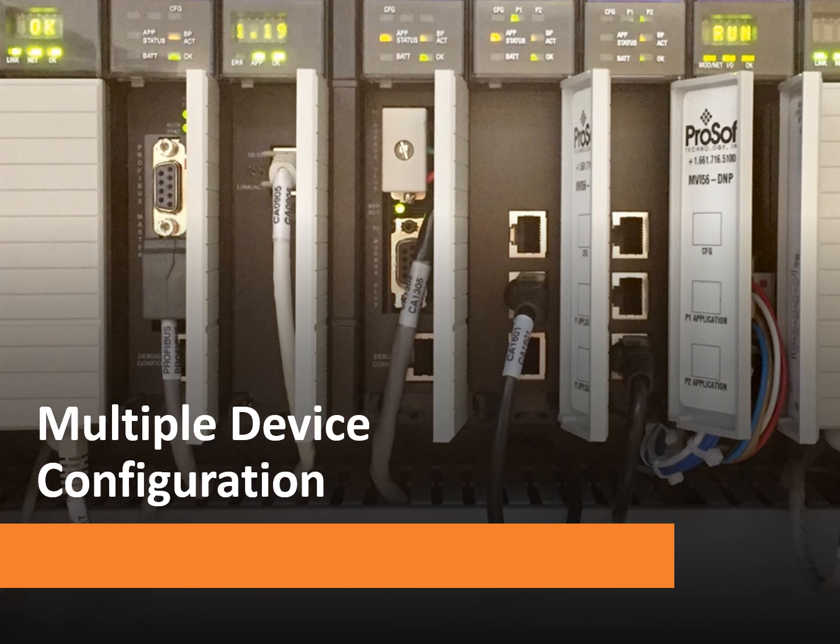The figure depicts multiple devices controlled on multiple networks. In this configuration, the ControlLogix chassis has 6 control modules. The DeviceNet module that controls a variable speed PowerFlex drive. The ControlNet module controlling a Flex distributed I/O. The Ethernet module that controls a distributed Ethernet ring network.